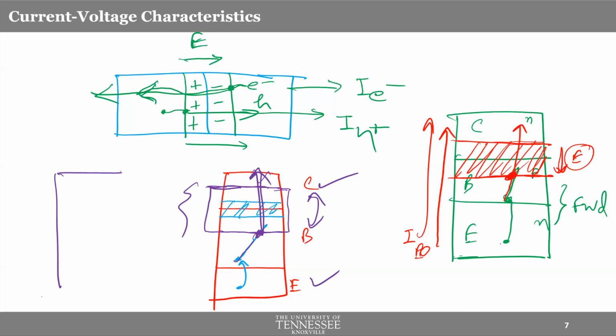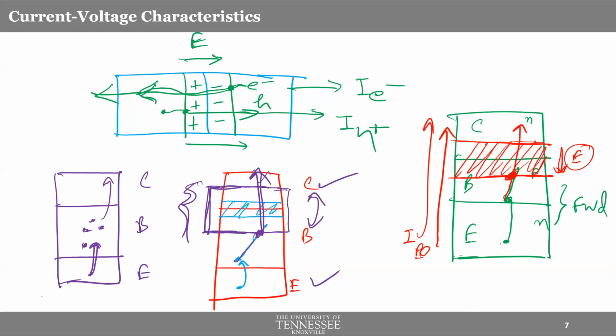Okay, so again, trying to draw a clear picture here. Emitter, base, collector. When the electrons go inside the base, if they spend a lot of time inside the base, there will be higher chances of recombination, and you will lose a lot of electrons coming from the emitter to the base before they can manage to go inside the collector. But by widening this space charge region, by applying a stronger reverse bias potential, you are actually grabbing these electrons from the emitter earlier, even before they can manage to recombine